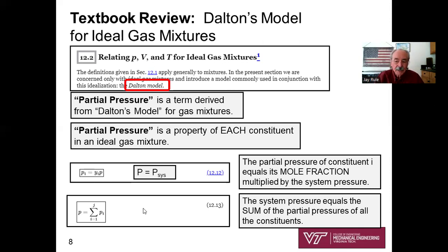That's a pretty easy concept, but you do have to learn that. You have to keep that in your mind. Partial pressures, what's the purpose of partial pressures? The sum of them is going to equal the system pressure. So if you have the mole fraction and you have the system pressure, that's very common, then you can calculate all of the partial pressures of each constituent.